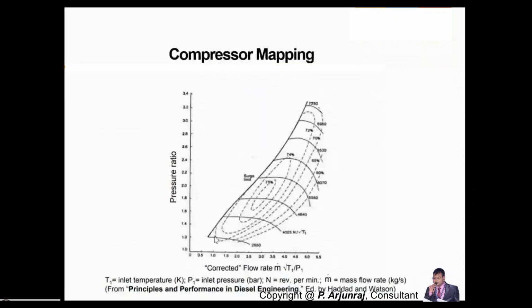And you see here, I told you the turbine RPM will be close to 1 lakh to 1,50,000 RPM, depending upon the speed, the airflow rate, and the mass flow rate of the gas as well. This indicates the RPM of the turbine, and this percentage indicates the efficiency of the compressor. And again you have a limit called the surge limit. This is the operating threshold limit.